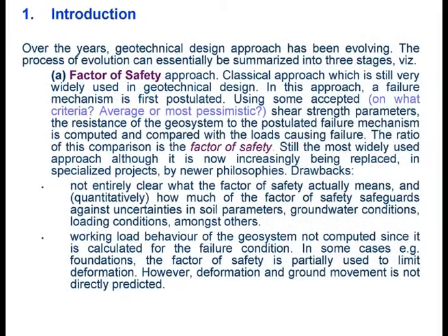The second thing is to talk a little bit about factor of safety. What is the problem? Really, the main problem is that the main use of finite element in practice is for people to come up with some numbers on ground movement and displacement. That's really one of the main things. And also to give some prediction on the bending moment on the walls, that kind of thing. So these are things that need something more than the limit equilibrium method. That is the reason why.